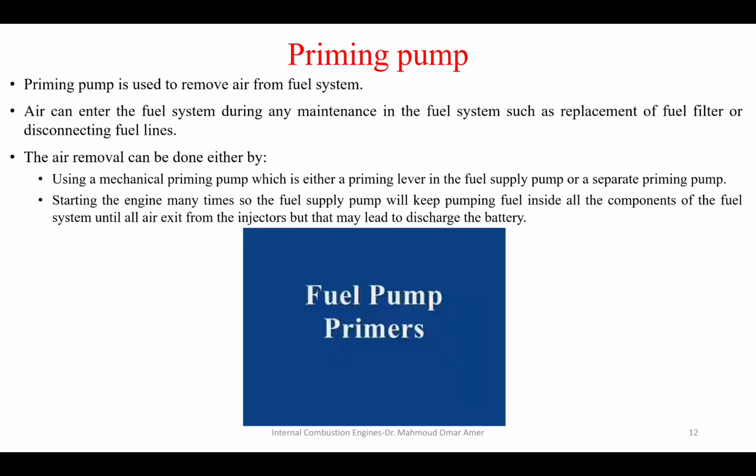That fuel entrance. When you perform any maintenance, like replacing the filters or replacing or repairing the pumps, air will enter the system. So you will have to prime the system and remove all the existing air from it.